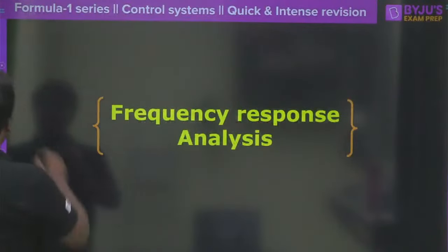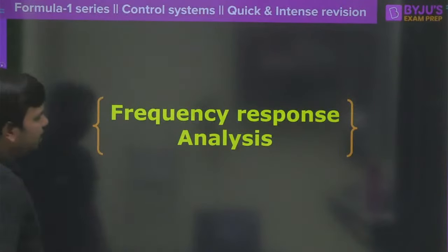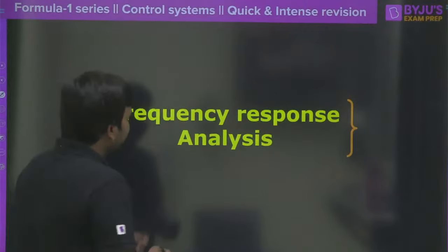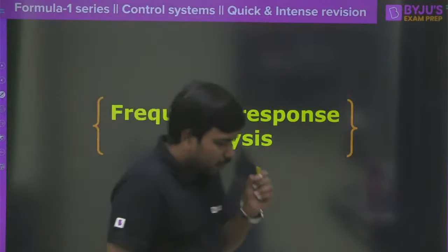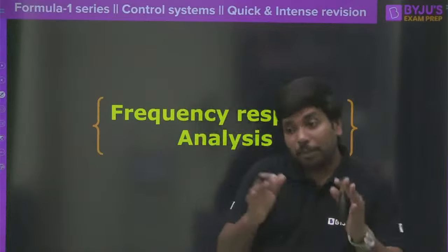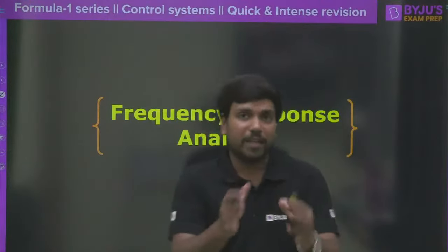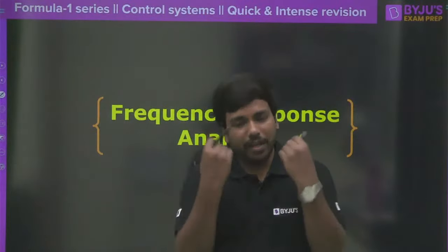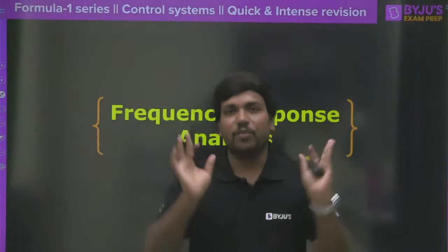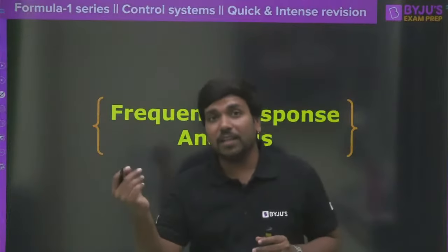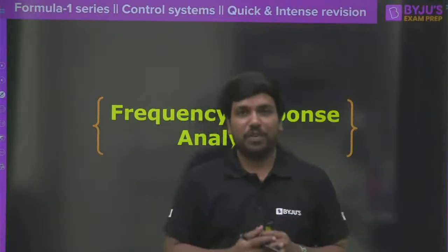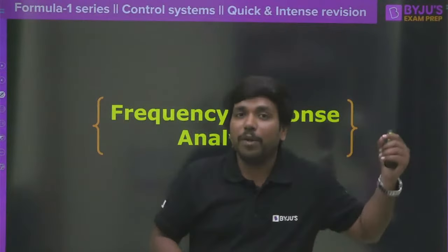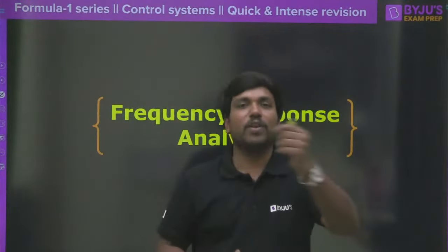Now coming to the frequency response analysis. What do you mean by frequency response analysis? Frequency response analysis means we apply a sinusoidal input to the system. That may be a first order system, a second order system, an open loop system, or a closed loop system. For any kind of system, we apply the sinusoidal input. And when we change the frequency of the input signal, the amplitude of the output as well as the phase will change.